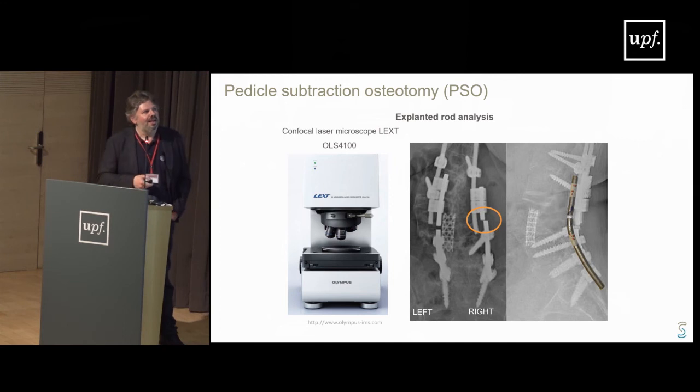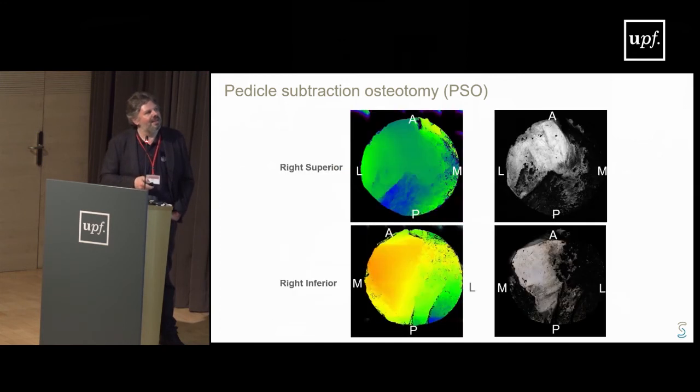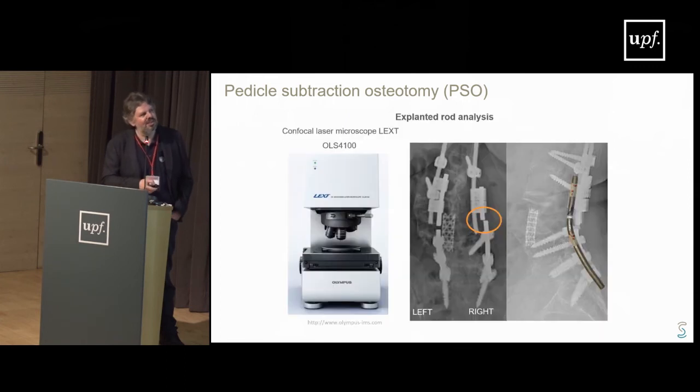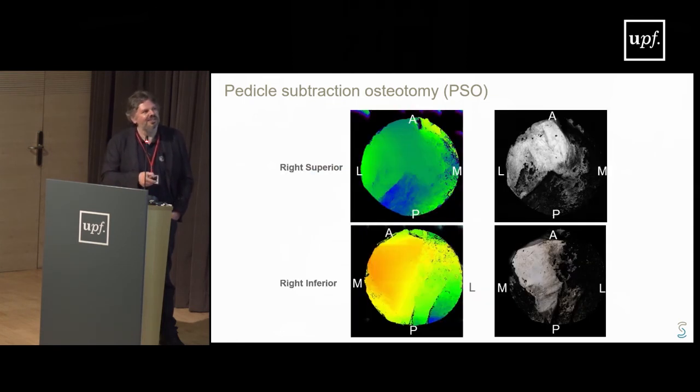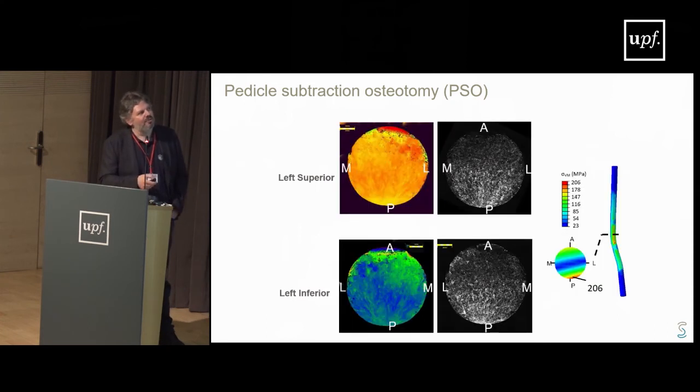And actually one rod doesn't tell us much, I would say, because you see here the two fragments were very close in vivo, and they touched each other, and they scratched the surface. So the fracture surface doesn't really say anything. It's just, let's say, polished by the motion after we had the fracture. But the other one was quite far away, and we can see clearly that's a typical fatigue fracture.